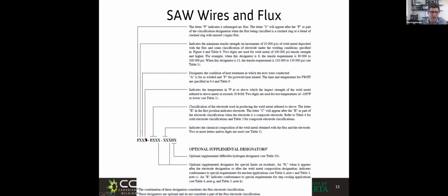It got interesting. And then there's something even kind of crazier. It's a number that says at what test temperature this gives you a minimum of 20 foot-pound in toughness, right? So if here we see a 6, it means at minus 60, we have 20 foot-pound.